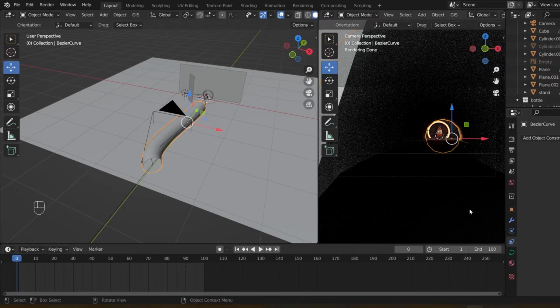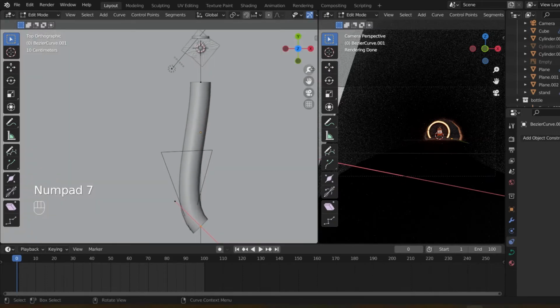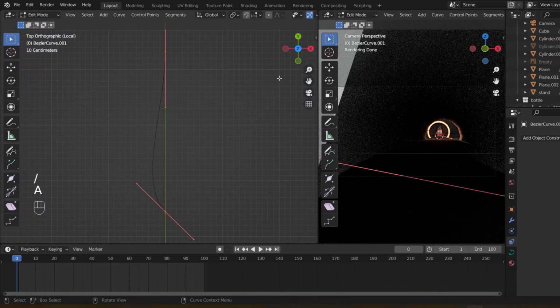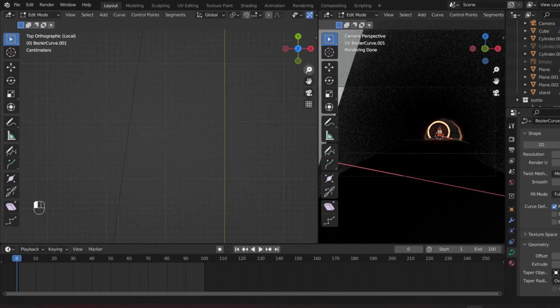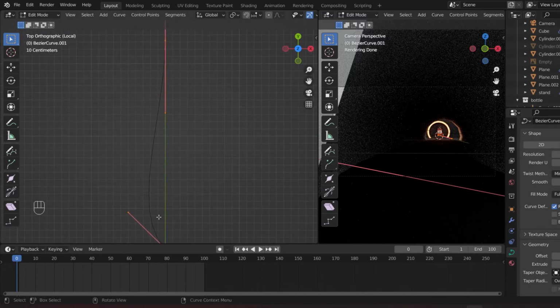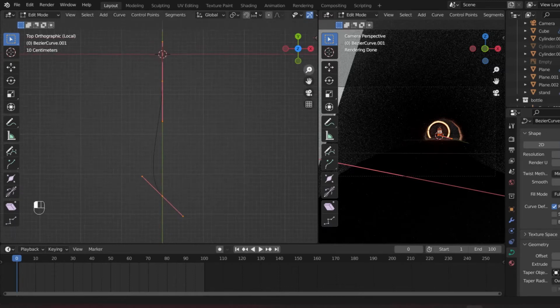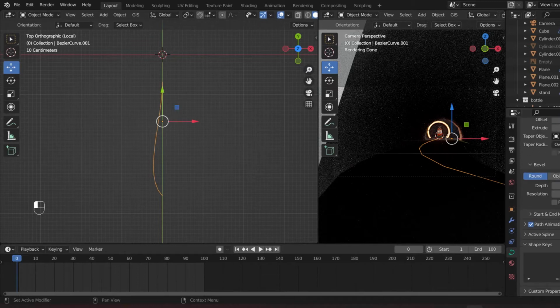And for this part, we're going to click the curve itself. I'm going to go into edit mode. In edit mode, what I want to do is make this a bit smoother, because right now if you zoom in, you might not even see it, but it's not going to be very smooth because there are just 2 points. I want it to be smooth. I don't want any breaks in the camera. So let me try using the geometry side. Yes, the resolution.